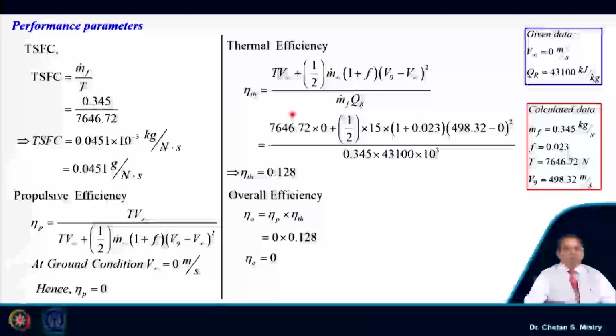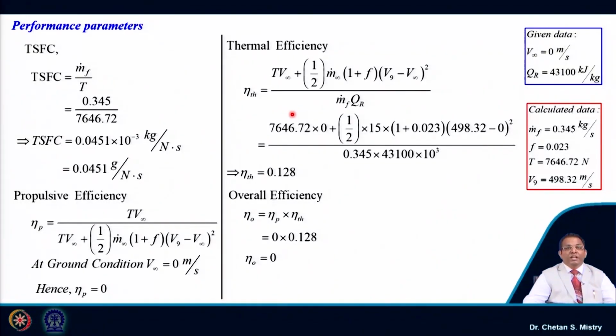Okay. So, you can understand what all we have done in terms of calculation of cycle parameters. When I say cycle parameters, it means what are my pressure and temperature at the entry as well as at the exit. Based on that, we try to calculate what is our exit velocity from the nozzle, which is very important in order to assess our performance parameters.